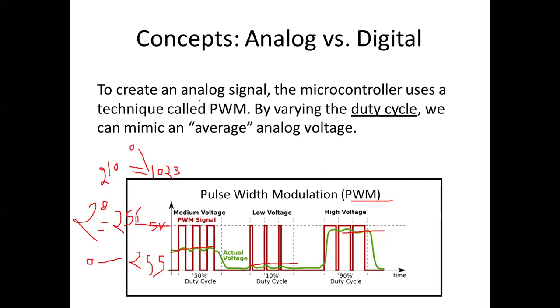Okay. So now what we have to do next: we are going to read the signal in the format of 0 to 1023, and that signal we are going to write in the format of 0 to 255 on analog output, because we want to control motor speed using the potentiometer. So how can we convert this value, because we are reading 0 to 1023, and how can we write it over here? We are going to see that in the code. Let's see it.